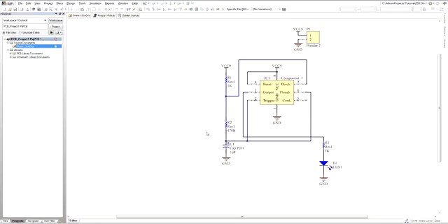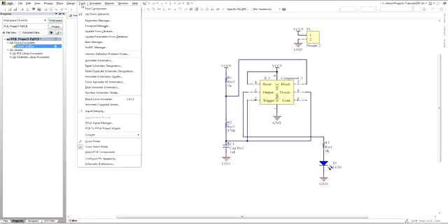And as you can see, I finalized the connections from the IC to all of our components, and I've annotated the schematic, which now shows R1, R2, R3, the cap, the diode, the IC, as well as the header. To do so, you've got to go into your tools, and you can either annotate the schematic manually by choosing which component gets a specific value, or you can just click on annotate schematics quietly.